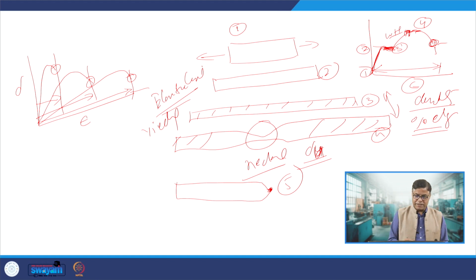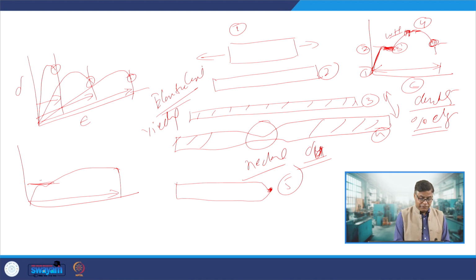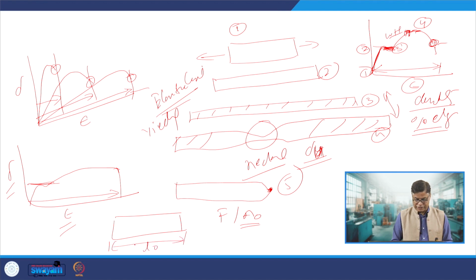So to cause plastic deformation for material processing, it is important that the material shows a lower yield point and greater elongation, then our ease of deformation will be high. But here, when the engineering stress strain curve is plotted, we assume that the load being applied is divided by the original cross sectional area, and to obtain the strain, we use the original length.